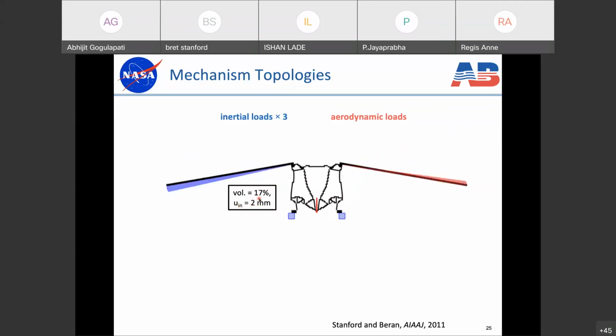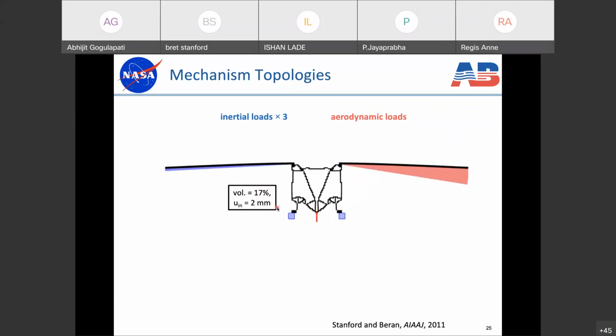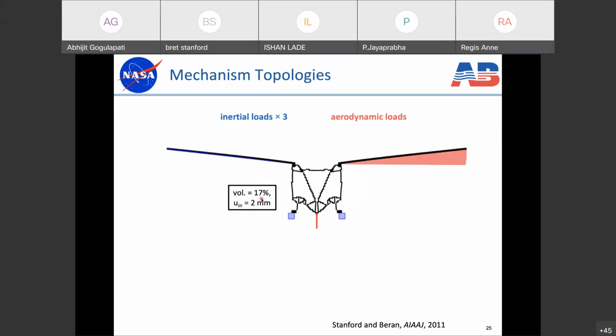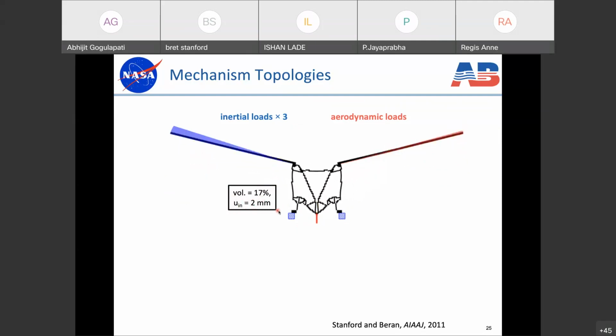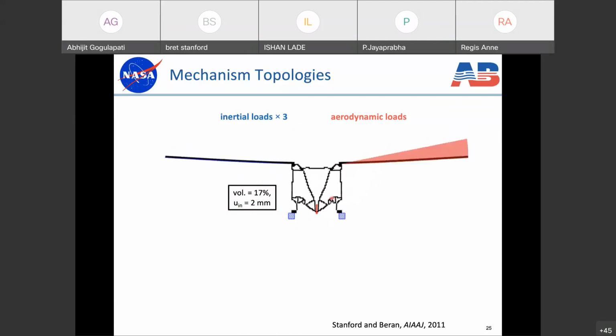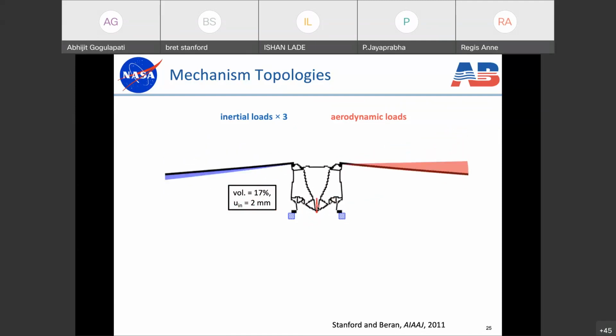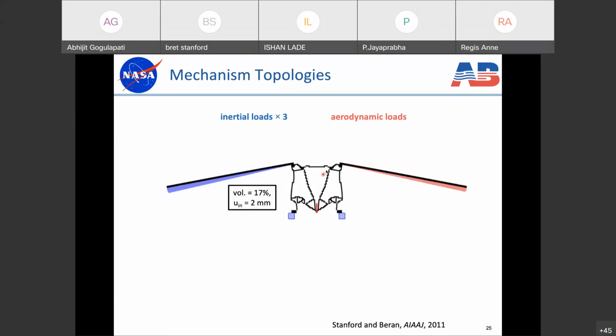We know from experience and from the compliant mechanism literature that if you don't put a constraint on this, the optimization problem becomes unbounded. And we can also change this constraint if we wanted, though I won't show that today, as a good surrogate for trying to limit the stresses that develop inside these mechanisms. So this topology is quite delicate, and it's quite complicated in the way that it works.